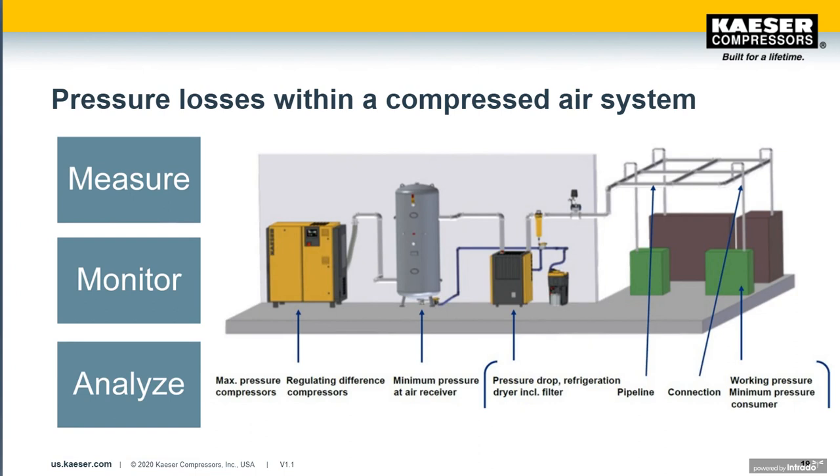For an ideal breakdown of operating pressures, these are going to be considered normal or optimized. If we have a 125 psi design compressor at the discharge, you typically have a regulation range of 10. So we're going to be seeing about 115 psi in that wet tank right after the compressor. Dryer filter, we would assume probably worst case scenario 8 pounds of drop.